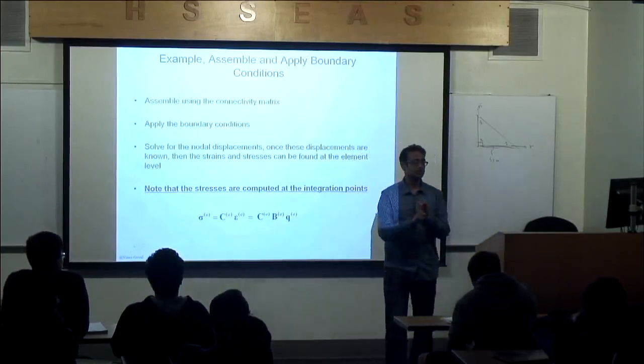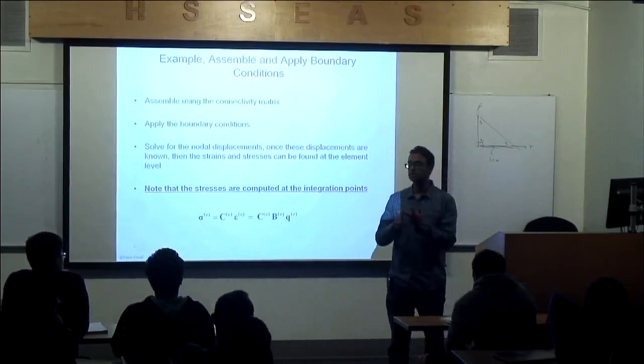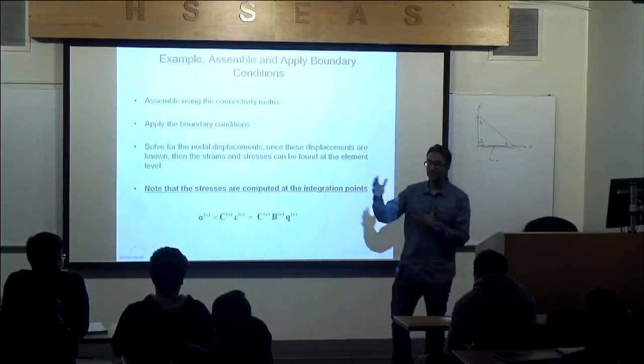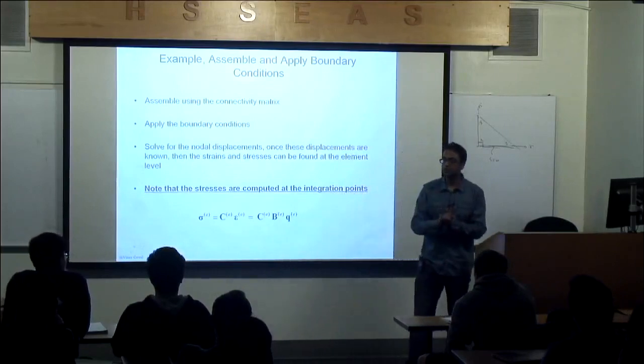Once you know stresses, you can now calculate the von Mises stress to predict failure of metal, or you can use a failure criterion of your choice if it's composites, right? Or max principal stress if it's a brittle material, and so forth.